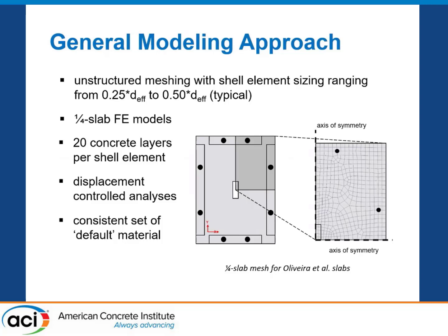This was the typical modeling approach. So these were all interior isolated connections, and in all cases we analyzed a quarter slab mesh just to make life easy. All analyses were done that way. All analyses were done with 20 concrete layers. All were done in displacement controlled analysis, and all had the exact same material models and analysis parameters.